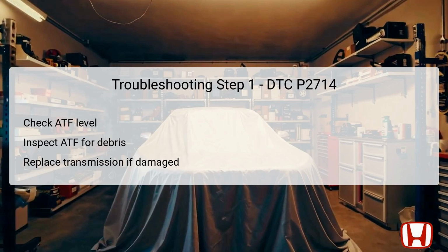If the strainer reveals metal debris or excessive material, replacement of the entire transmission is warranted. If there are no contaminants identified, proceed to replace the ATF and continue troubleshooting for further diagnostics.